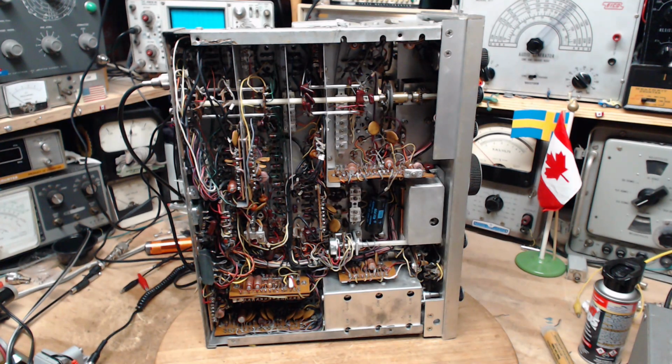If the 230 IF is being muted, then the problem is the mute system. And in this great big complicated radio, it's just a little tiny area down here that's really potentially in trouble. So let's start by taking a look at the schematic, and maybe I'll go get some coffee in the meantime. Ooh, that's a good idea.